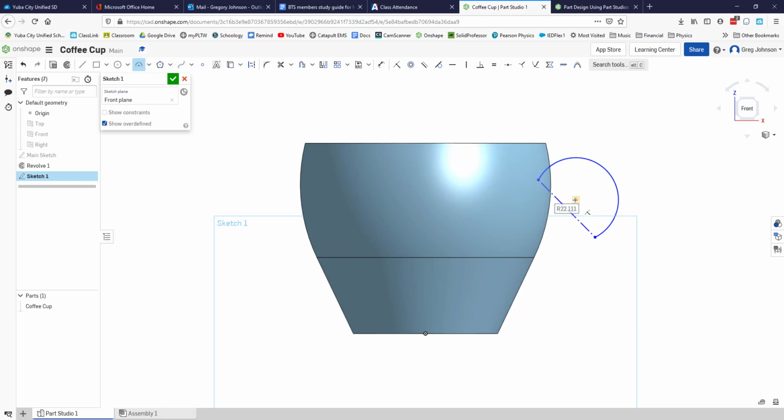And now I'm going to make this coincident with this. So I'm going to hit coincident, the center of the arc, and the construction line. And finally, I'm supposed to make another line that would come off that out here somewhere. And if you notice, if there's a constraint that appears that is perpendicular to that line, I actually do want that constraint. So I'm going to click over here.